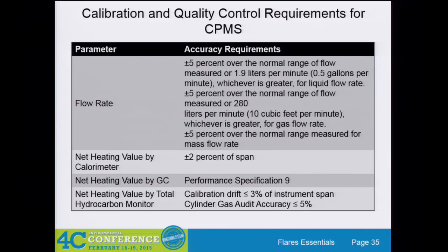This was one that we were so frustrated about again, because enforcement knows about the flow meter accuracy issue. We need the 20% from 1 to 0.1 feet per second. Did they do it with the proposed rules for Max EC? No. Even with the comments that went back on NSPS JA about the flow meter requirements, they did not change it. They still went with this 5% over the normal flow range. So it's still going to be an issue.